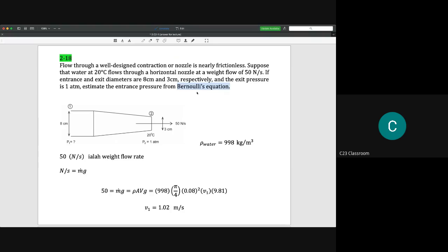I think you already heard about the idea of isentropic flow. So you have equations for P2 over P1, T2 over T1, and so on. So you need to calculate the Mach number and so on. The limit is if the velocity is around 0.3 Mach number, meaning only 0.3 times the speed of sound of that medium. If less than 0.3 Mach number, you still could use the Bernoulli equation in your calculation.